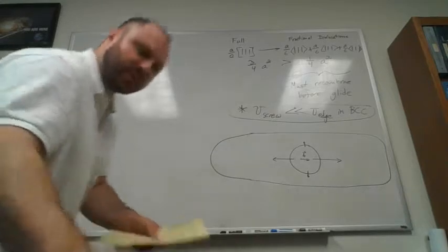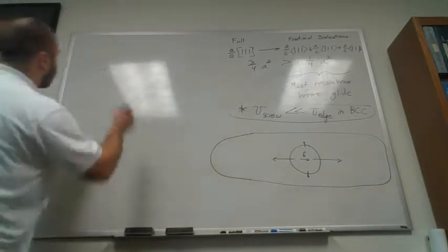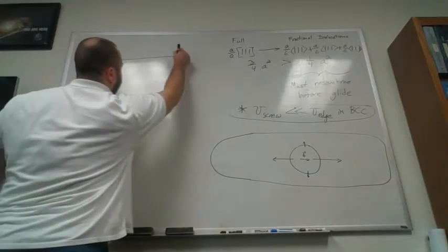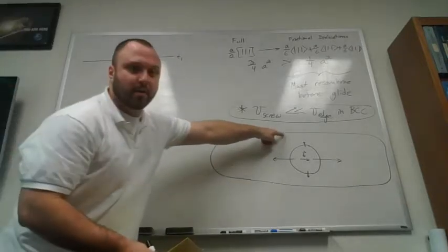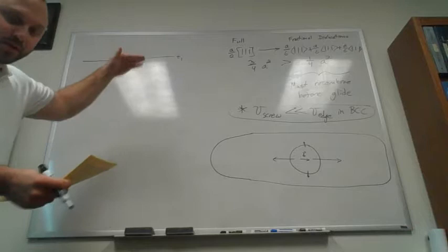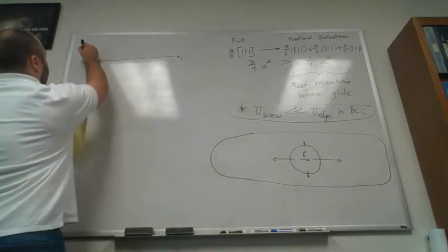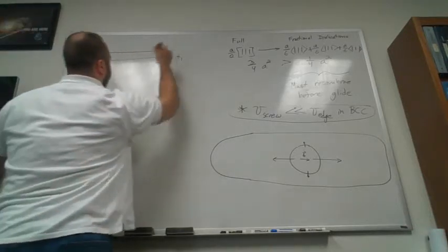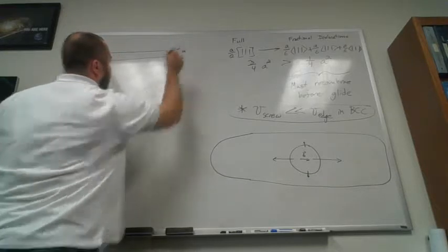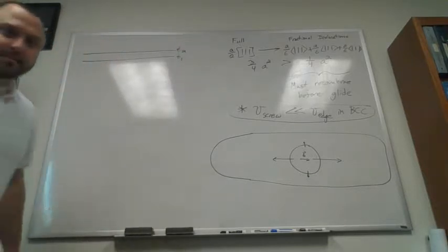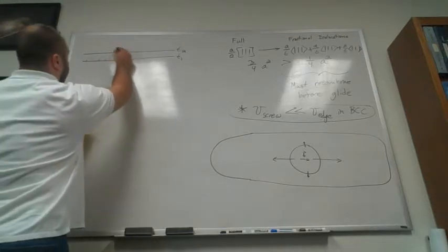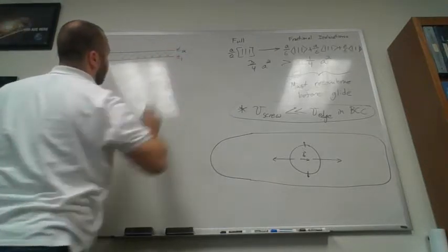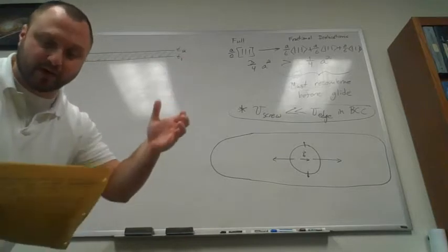So you can think about dislocation moving in 2 different ways. We could say this screw dislocation at time 1, this top part right here, it wants to move up 1 step. So one option is it moves up 1 step by time 2. But that means that along this whole length, it needs to recombine and move up.